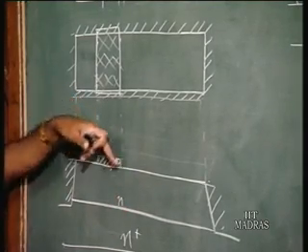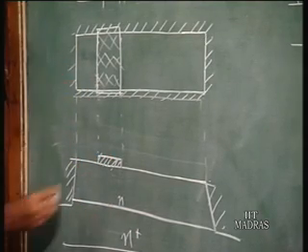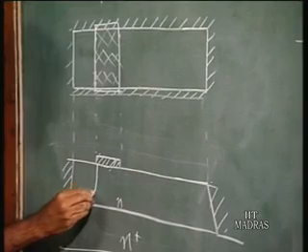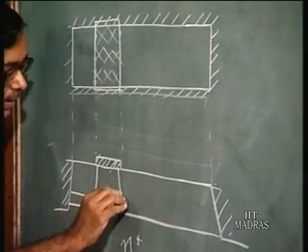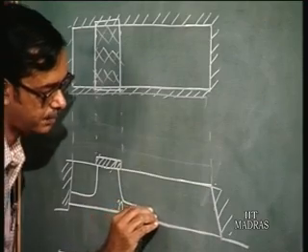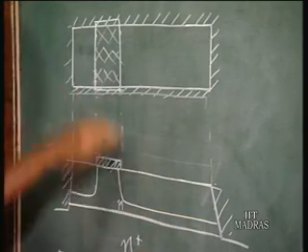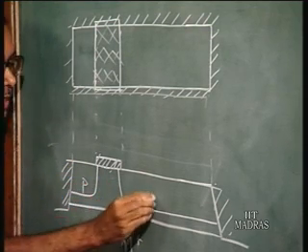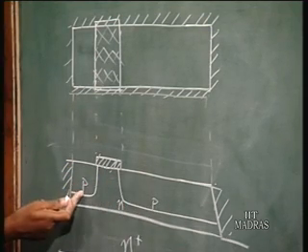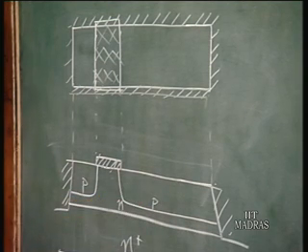So here silicon dioxide protects this region when you do an implantation. So what you have is a p region here, and another p region here. These are the exposed regions. So this is a p and this is the p. You can identify that this is for the injector p diffusion and this is the base region for the NPN transistors. So this is done.